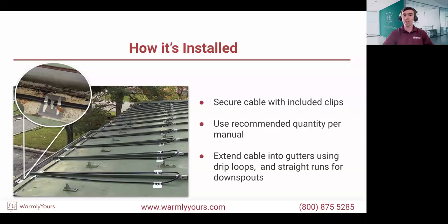Because if we're talking about a heavy mixture of snow and ice suddenly sliding off the roof, you can only imagine the weight and force that's happening there. And let's just say you did not secure the cable as required in the instructions, that force of snow or ice sliding is very likely going to take the cable with it. So you don't want to take chances and install the cable, spend all that time and money for that application, but then not treat the roof as it still should be treated with the proper snow guards. And then suddenly you get to the point where that snow slides and takes the cable with it.